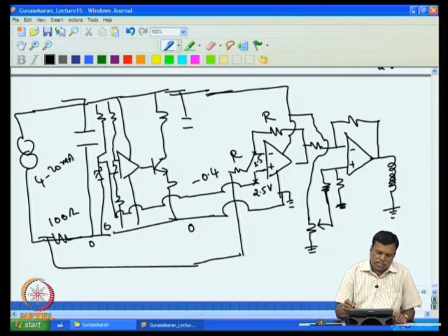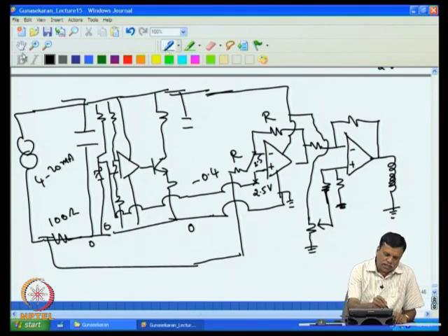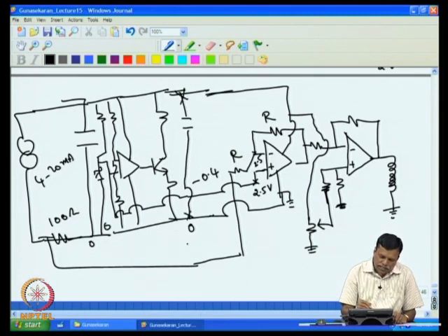So in this example, we have designed a circuit starting from this 4-20 milliampere. So what we have done is the 4-20 milliampere current that is flowing here in this is converted into a regulated voltage. So that's what we have done here. So we got a regulated voltage across this point, say that is 10 volt. Now then this is the one which gives you the signal, because this represents what is the total current flowing. If they want the actuator to be at 50% level, they will be sending 12 milliampere current.